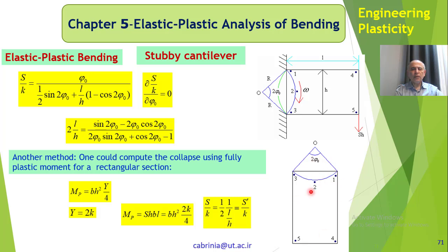Now what is this? This is the hodograph for this diagram. Now I have put many points here, point 1 there, point 2 there, point 3, point 4, point 5. Okay, obviously this beam, when it fails, it only revolves around here, it does not deform in any other way.